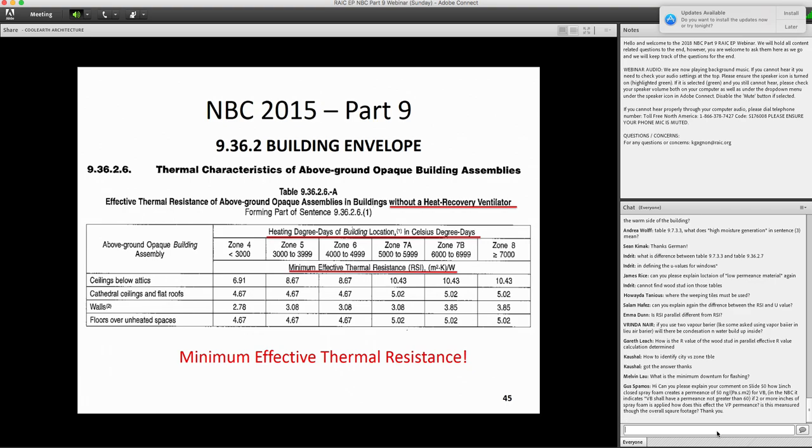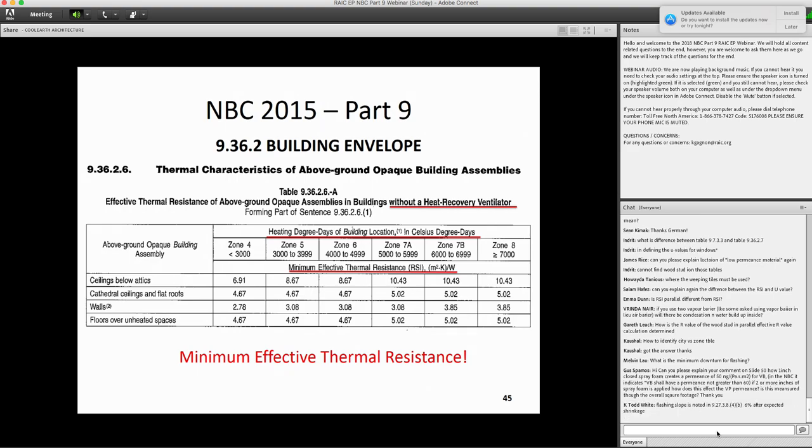If you fully use spray foam up to the vapor barrier, you're safe. But if you have exterior insulation and you have other components and then you have the vapor barrier, you're going to generate potential problems. That's mostly a building science thing. It's not in the code, but it's interesting to know that.